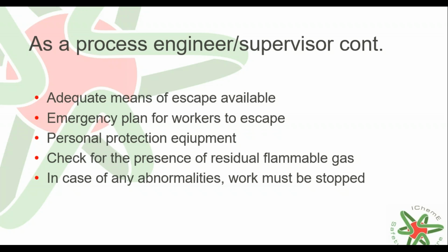Use of nitrogen to purge lines should be considered, but used with caution. It could cause pyrophoric deposits to dry out, and therefore increase their flammability. Working areas should be drenched in water until open pipes have been blanked or spaded. In case of any abnormal situation, meaning a leak or, for instance, rupture, work must be stopped immediately and shouldn't start again until a thorough inspection determines it is safe for work to continue.